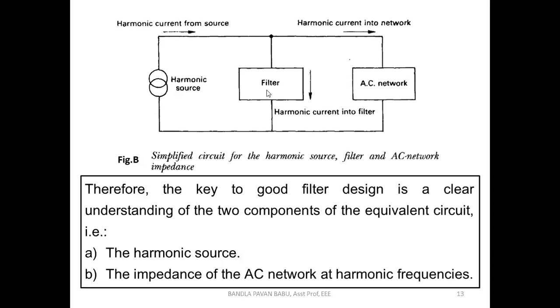But from that equation, we can say that if the reactance is made completely zero, a high amount of power will be delivered for a short period of time. That should not happen. By placing the filters, a resonance condition should not be created in the line, so certain measures must be taken. As I said before, if the total reactance is high because of inductive reactance, we need to compensate with capacitive reactance. If the capacitive reactance is high, we compensate with inductive reactance. That is what we perform with the help of FACTS devices.